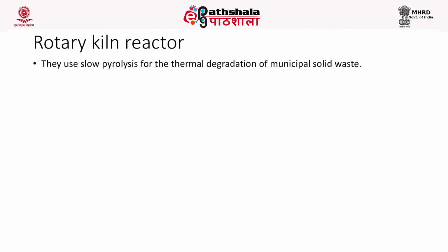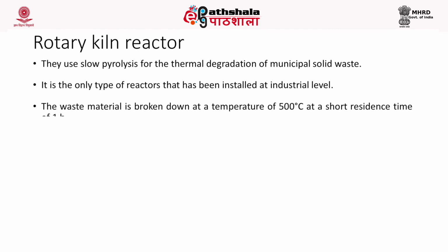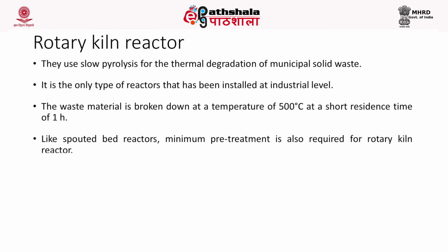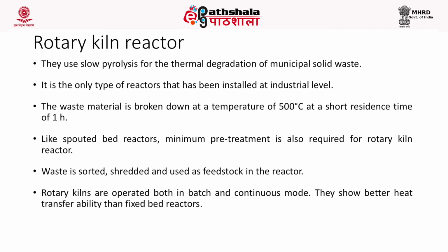The next type is the rotary kiln reactor. They use slow pyrolysis for the thermal degradation of municipal solid waste. It is the only type of reactor that can be used at an industrial level. The waste material is broken down at a temperature of 500 degrees Celsius at a residence time of 1 hour.